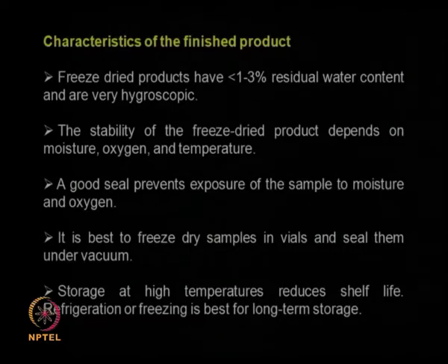So what are the characteristics of the finished products? Once I have done some lyophilization, the amount of residual water present may be in the order of 1 to 3%. The stability of the freeze dried products depends on the moisture present, oxygen, and temperature. But if you are freeze drying vials and you have a good sealing system, you are preventing exposure to moisture and oxygen. So it is ideal to do small samples in vials, so we can seal them under vacuum.